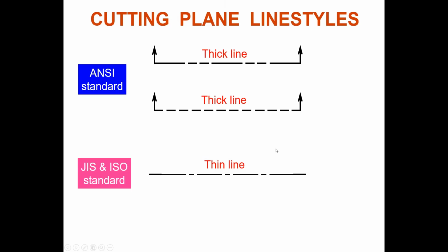Clear. Good. But you see at the end here, the thicker, the bold. Okay? So you must have an arrow, I'll show you an example. There must be an arrow showing direction. The arrow is like your dimension arrowhead, but bigger. Remember when you make your dimension, you have an arrowhead, right? I always mention the ratio is 3:1, but this is a little bit bigger scale.